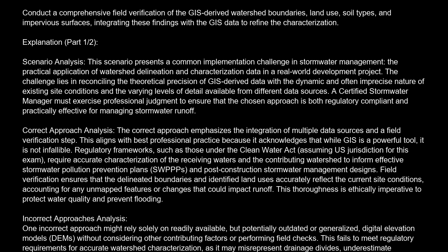Field verification ensures that the delineated boundaries and identified land uses accurately reflect the current site conditions, accounting for any unmapped features or changes that could impact runoff. This thoroughness is ethically imperative to protect water quality and prevent flooding.